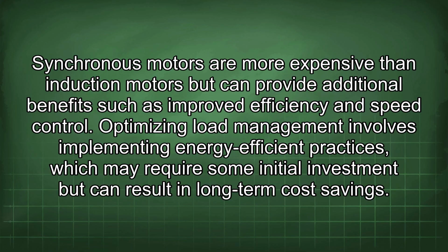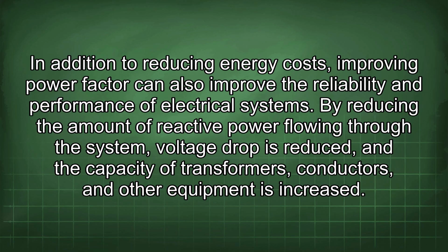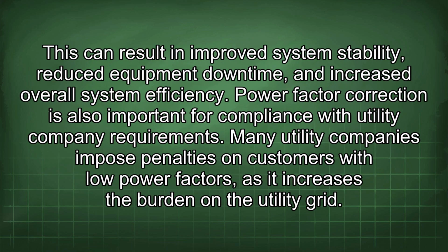In addition to reducing energy costs, improving power factor can also improve the reliability and performance of electrical systems. By reducing the amount of reactive power flowing through the system, voltage drop is reduced and the capacity of transformers, conductors, and other equipment is increased. This can result in improved system stability, reduced equipment downtime, and increased overall system efficiency.